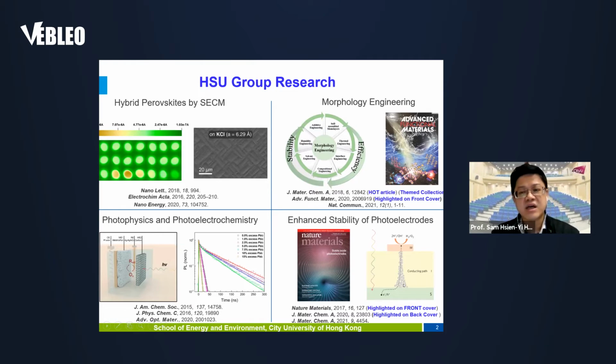After treating with this localized breakdown process, we produce this conductive pathway. In other words, we can increase the stability by increasing the thickness of the insulator, and simultaneously enhance the efficiency by the breakdown process due to this conductive pathway.